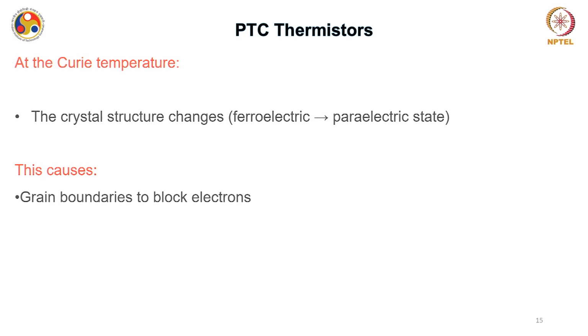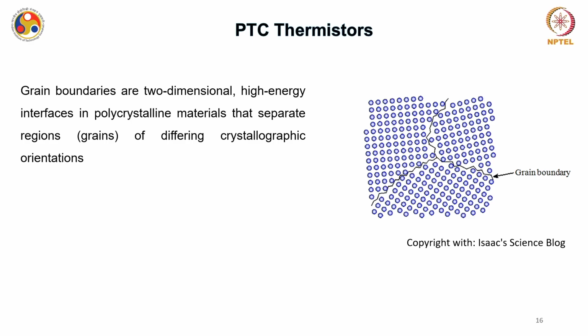And again, if you are not aware of grain boundary, I will suggest that you read about the defects in any crystal structure. Okay. So, we have different defects in case of any crystalline material. You have 0D defect, you have 1D defect, you have 2D defects, you have 3D defects and so on. 0D defects mostly cover the vacancy and other things. Okay. While the 1D defect mostly is known as the line defect. Okay. And sometimes you have dislocations in this category, while the 2D defects have various defects including the stacking faults and the grain boundaries. Okay.